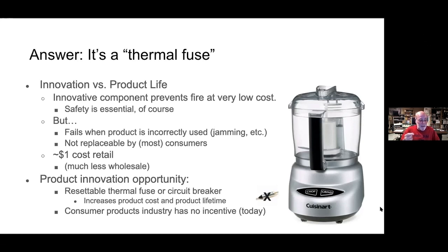They're really not replaceable. You can buy them for $1 retail. When we used to have a place called Radio Shack, they used to sell them. Now you have to hunt on Amazon or eBay to find them. I actually bought a big bag of them of all different voltages and currents and temperatures. They're designed to, the 192C says, ooh, if this environment goes above 192 degrees centigrade, then open up. So they're rated for different things. $10 for 100. I mean, I have plenty. Bring them to all the clinics.